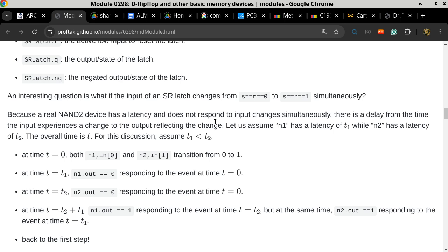But it is a good exercise, because in that exercise you will understand why. Otherwise, people look at this circuit and go, oh, we can just try out everything in Logisim and understand the behavior of the circuit. Yes, with simple circuits we can do that. But Logisim cannot figure out that the circuit has entered a state that is oscillating, which is not going to be a steady state anymore. It's only through the analysis that we have done, separating the two phases, NC, node connectivity, and PD, propagational delay, that we can find out that this circuit will never settle on a steady state ever again.